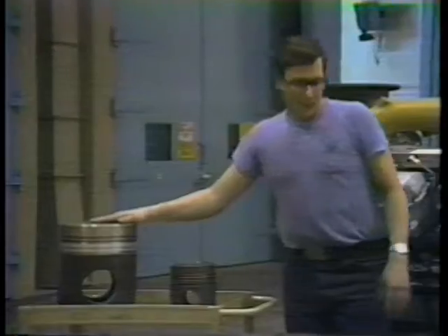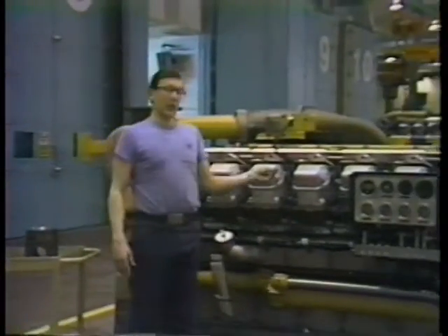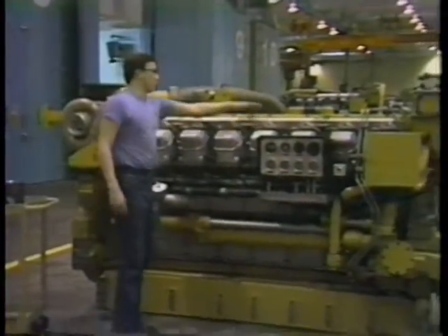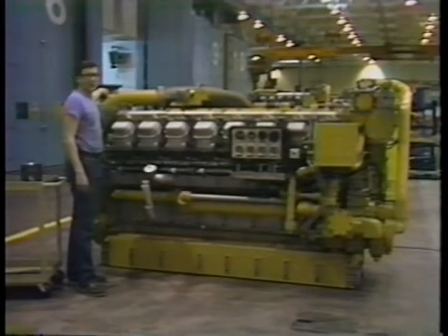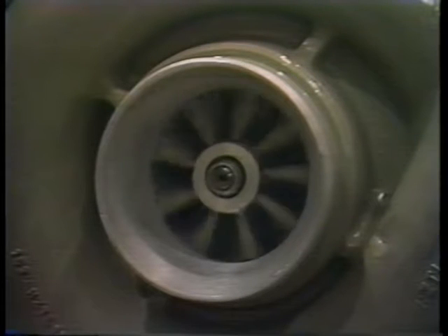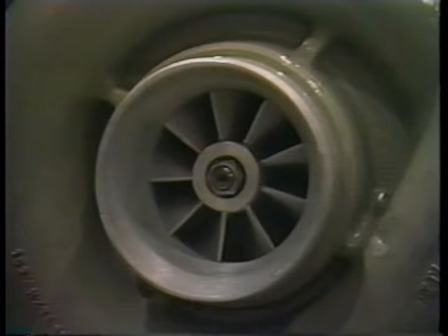After this gas drives the piston down into the cylinder, we collect the exhaust gas through the exhaust manifold, and this exhaust gas drives a compressor turbine, and it draws fresh air and actually runs in a boost condition to feed these cylinders so they don't have to draw air in through a vacuum, and makes it more efficient.